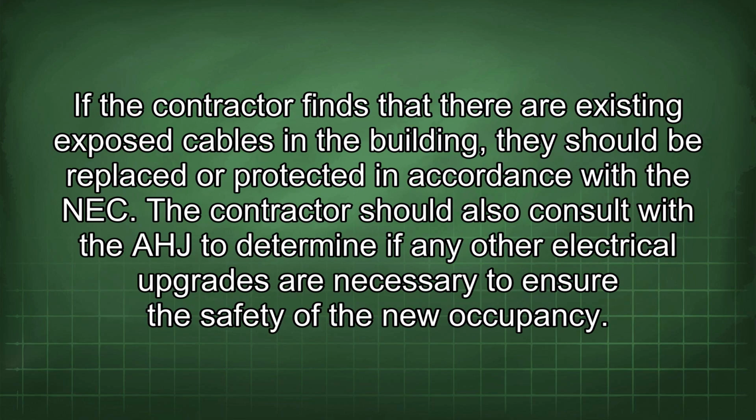If the contractor finds that there are existing exposed cables in the building, they should be replaced or protected in accordance with the NEC. The contractor should also consult with the AHJ to determine if any other electrical upgrades are necessary to ensure the safety of the new occupancy.